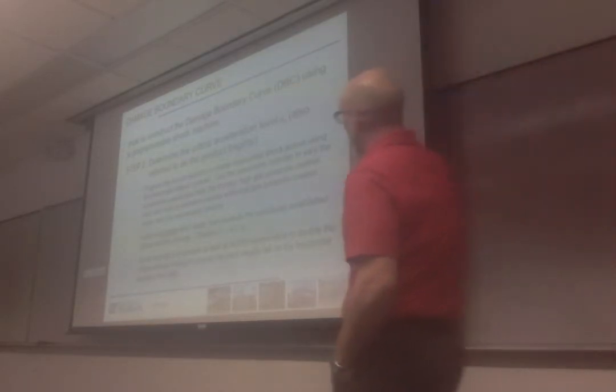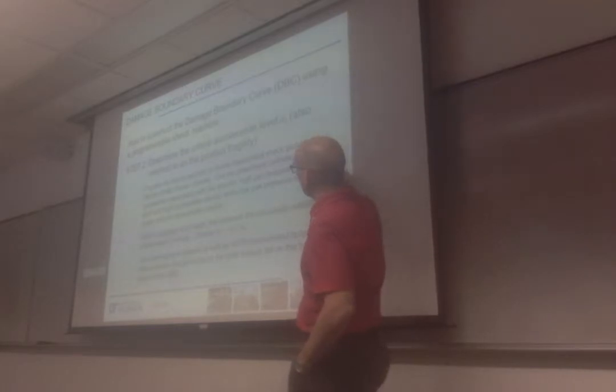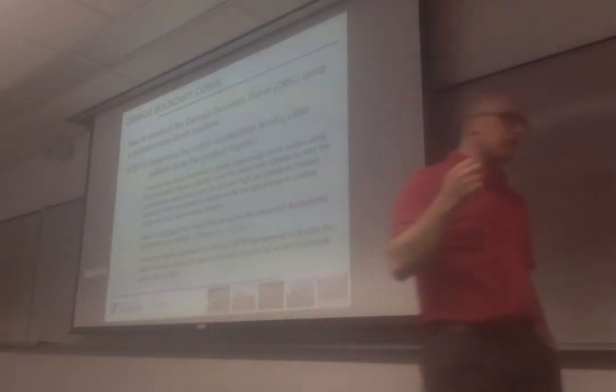So in this one, we create a trapezoidal shock pulse. You want to do this because these carry more energy. That's the maximum energy you can carry for a certain acceleration level. Think about this: this is what is closest to a square waveform.